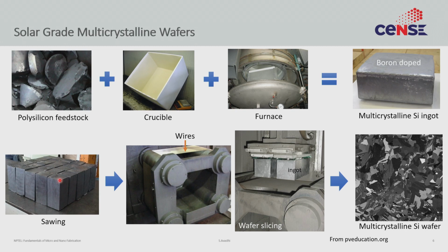Schematically, I think I mentioned this when we were talking about wafering in the first few lectures, but here I'll give you the images of the actual machines. So this is what the machines look like. These are the rollers. You see this shiny part on the top and this taut point on the sides. These are the wires. These are very thin steel wires with impregnated diamond in them, and these very thin wires are what cut these cuboids into wafers.